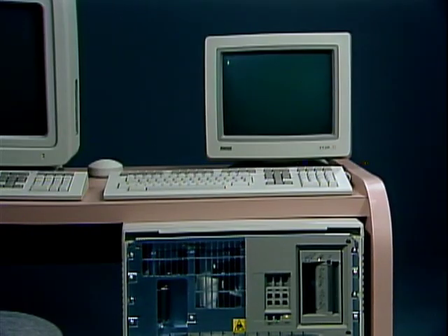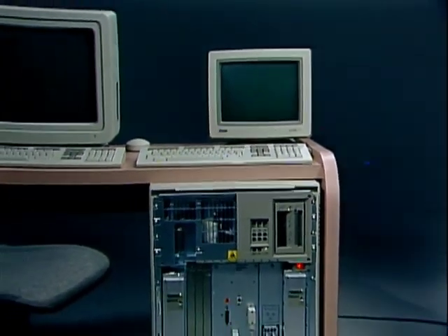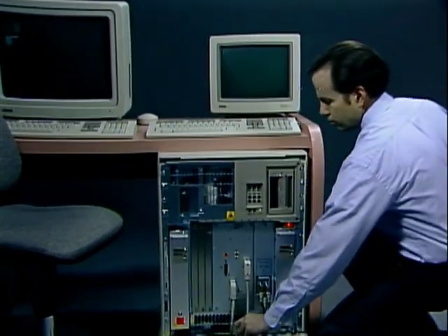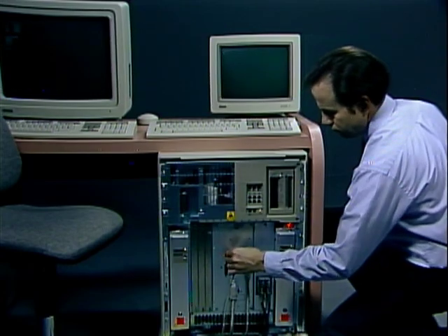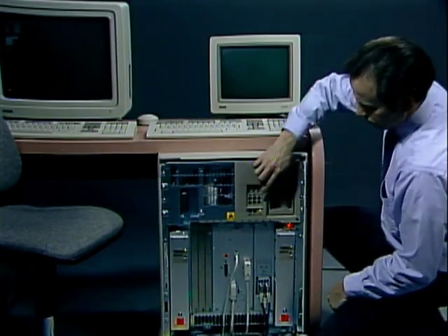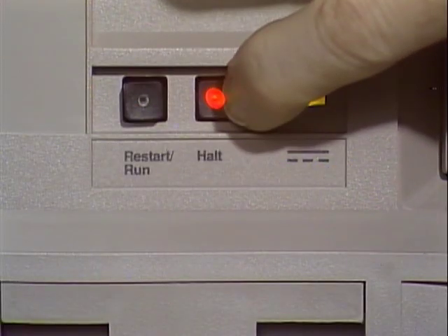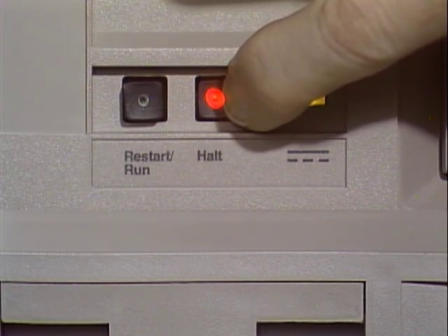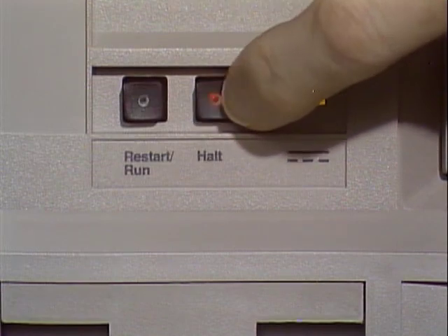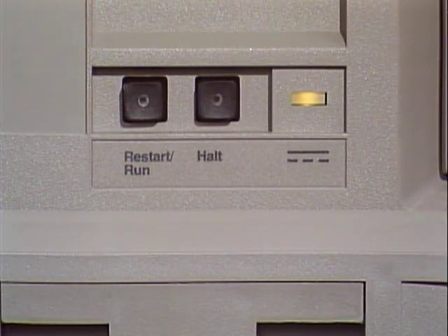If you suspect a problem with a monitor or its cabling, you can use an alternate terminal such as a VT330 as the console terminal. To do this, connect the alternate terminal to the printer port of the I/O cover module. With the system in console mode and the terminal powered up, push the halt button in and hold it there. The green LED on the restart run push button will begin to blink. After about 6 seconds, the LED blink rate will increase. When this happens, release the halt push button.